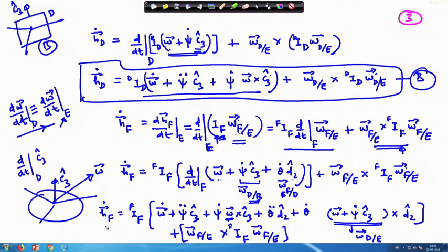So, this constitutes your the angular equation for the f 1, the frame f, and thereafter we have to write the equation for the wheel. So, you can see that how much complication is arising. If you take the exact equation for the CMG, control moment gyros, and that too we are assuming that the center of mass of the control moment gyros and rest of the satellite it is coinciding. If you do not assume that, then the equation will be further complicated.